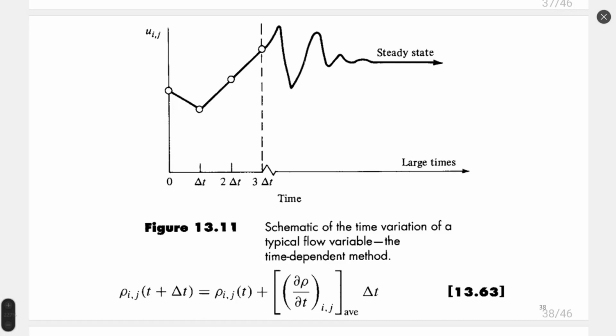So when it goes to steady state, residual is 0. Residual is the difference between different time steps of each flow property. For example, the residual of mass is the difference between densities at two different time steps divided by the time step. Delta T is basically the time derivative, dimensionless. And here is a dimensional flow property, some velocity, for example.